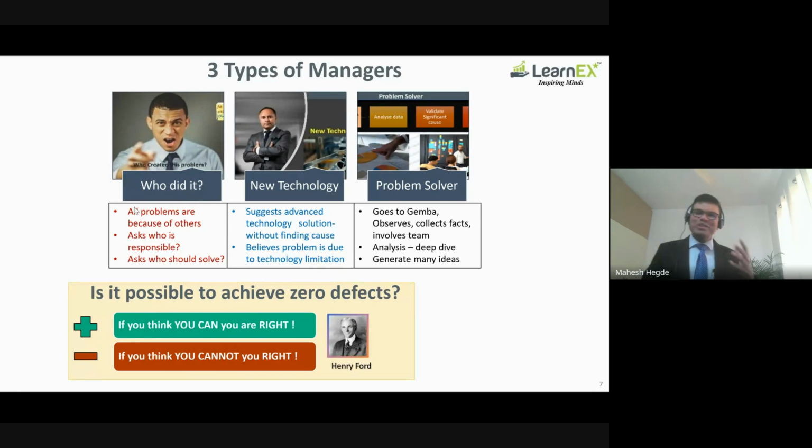The cause was not in the engine. The cause was in the test bed. We just used the measurement system analysis range method, and their R&R percentage was extremely high. Then we came to know that the engines are really good, not a problem, but the problem is with the test beds. Then which test bed? Why is there a test bed to test bed difference?